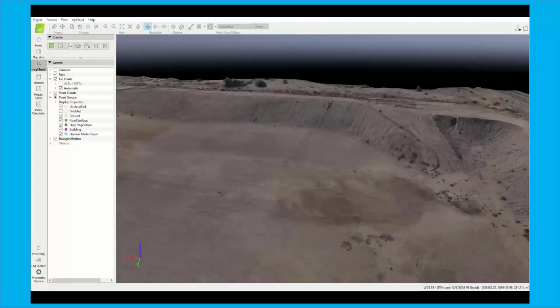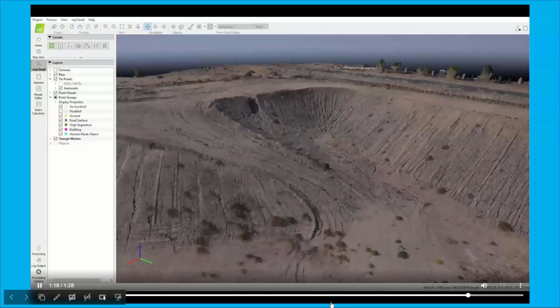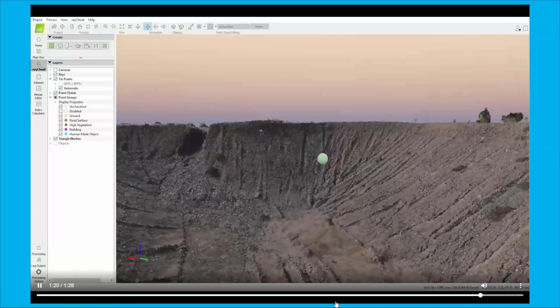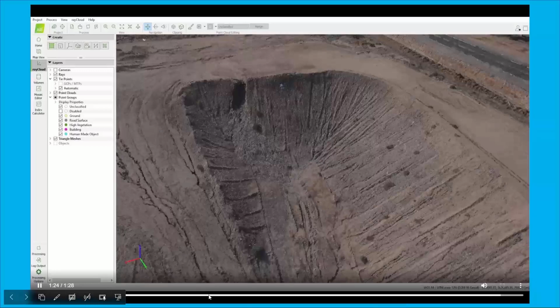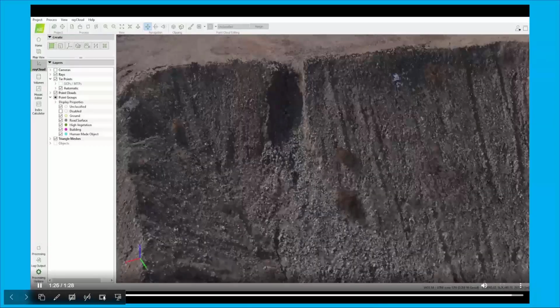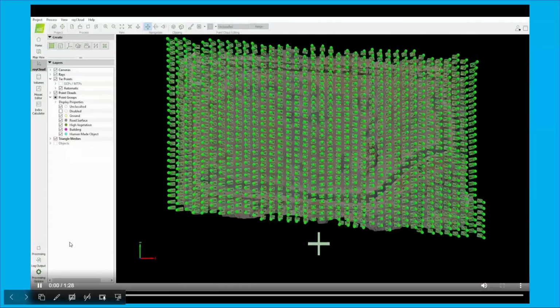You can make the polygon for your data, where you're collecting the data, anything you want. The automatically generated waypoints automatically set all the camera triggers and distances. You're just tweaking things like altitude, tweaking things like overlap and side lap. For our plane, we typically set that at 70% on both.